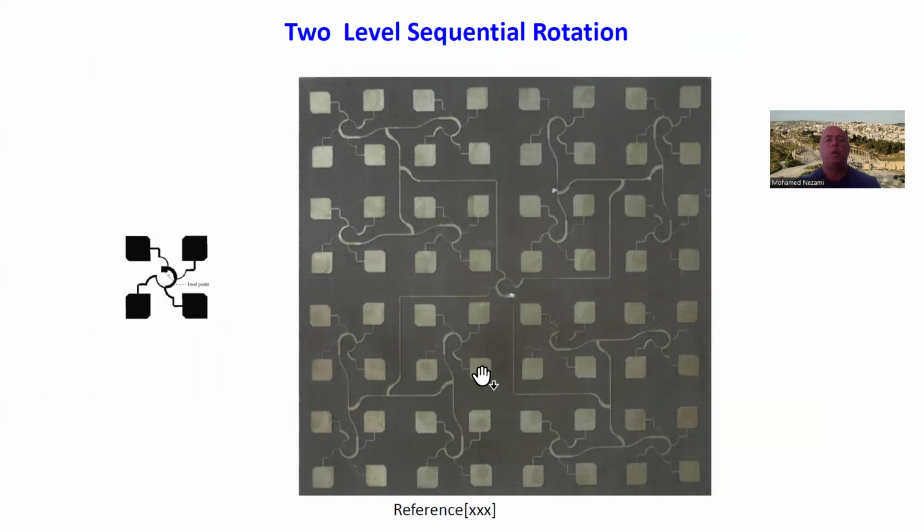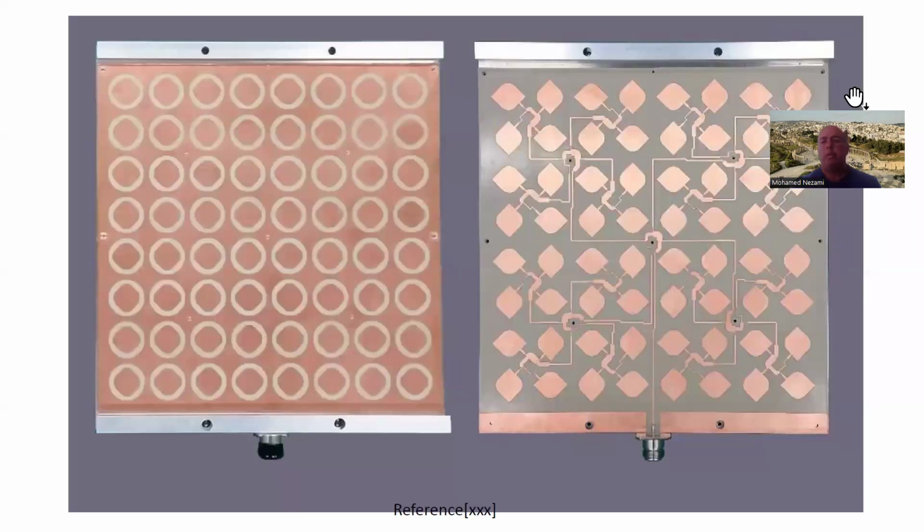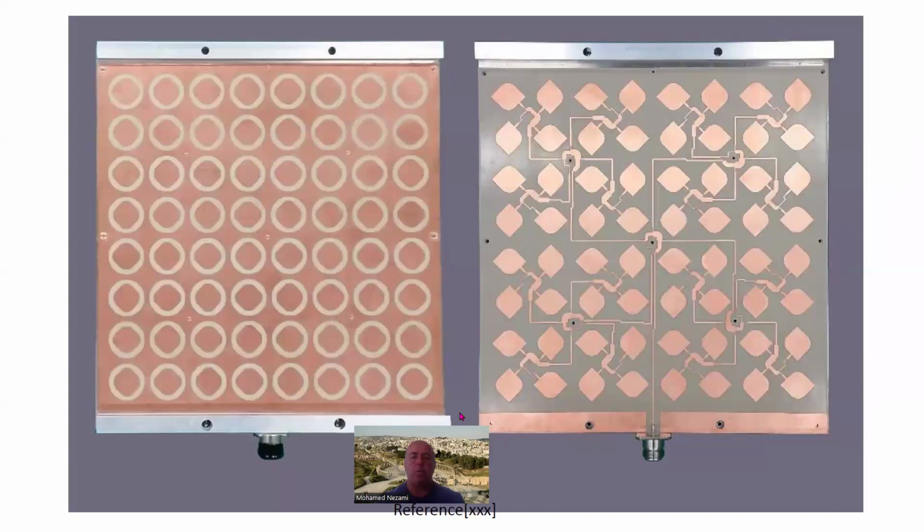So this is, again, right-hand side. There's another example here that shows the array, the elements, and these are just the parasitics on top, loading these ones. And you can see again we're feeding exactly the same way. We're coming in through this coaxial connector, feeding this one first, and then this one, and this one, and this one. So this one is going this way. So this is counterclockwise, so this is left-hand side, right-hand circular, left-hand circular polarized.